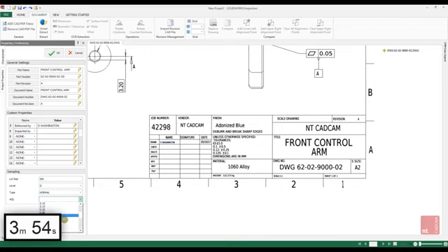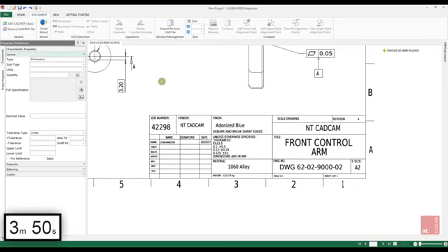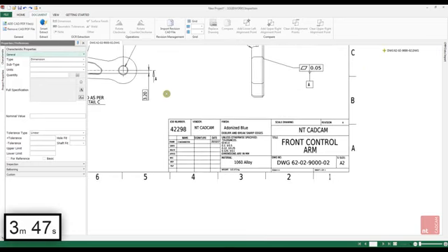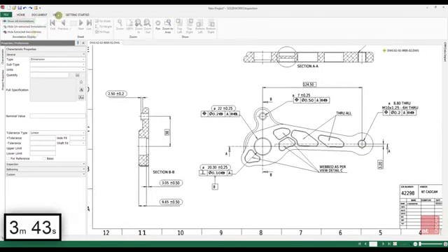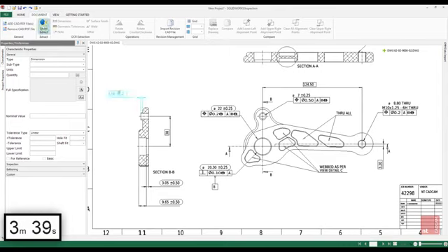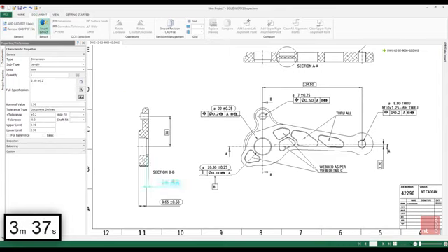And now we're just going to set our sample size and our AQL level of 2.5%. We're now going to start extracting our annotations using the Smart Extract tool. But first of all, we're going to make hidden the annotations that we've already extracted as a characteristic, which makes it far easier for us to see which annotations we've extracted and which we have not.